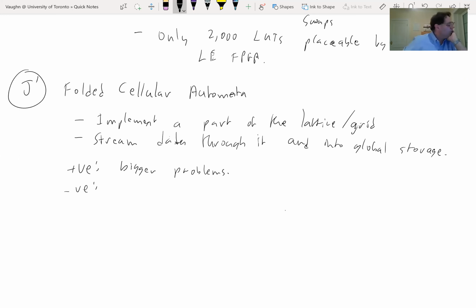so I see a couple of interesting questions. So what's the optimal size for cellular automata? So I guess basically with this architecture where you're folding it, like you're basically building a certain amount of the grid, you would build as much as you could. You are faster and more efficient if you can do as big a chunk of the grid as possible, which is generally still going to be a pretty small part of the grid. Maybe it's 1%, but you will get better performance if you do 1% than if you do 0.5%. So you're basically going to fill the chip is what you usually do. Basically you've gained capacity by doing this.